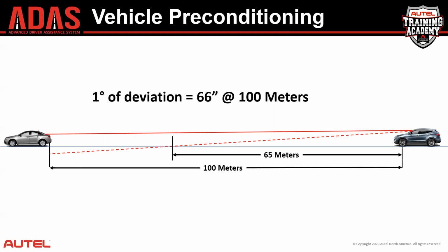So very, very critical. You have to think about how the systems work, not just what you think they do. Changing a windshield and calibrating a camera doesn't mean that camera's only being utilized for lane departure warning. We have to think about all the systems and sensor fusion and how everything is integrated.